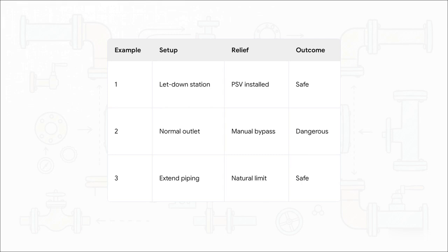The piping is rated for 10 bar class, the spec break is right after the control valve assembly, and if the valve fails mechanically open, the PSV lifts and safely relieves the capacity. This is legitimate, code-compliant, cost-saving design. Now look at example 2. The upstream source is 25 bar.